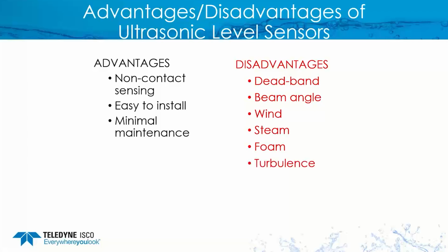And last, turbulence. So if the flume is installed in the proper location, you shouldn't have turbulence here. But sometimes you don't have enough room, it's mounted too close to a bend, you don't have the proper straight run, and you may end up with turbulence, or there's debris in the bottom of that channel, which is creating your turbulence.